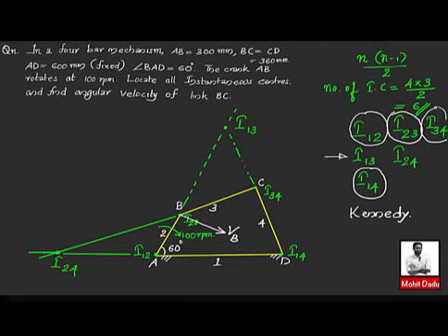Similarly, link number 4, or link CD, the output link, is also having a pure rotation about this point, the instantaneous center. So this will have a velocity vector perpendicular to the line joining C and D in this direction. That velocity vector I will mark here and name as velocity of C. With respect to D, which is a zero velocity point, I will simply name it VC.